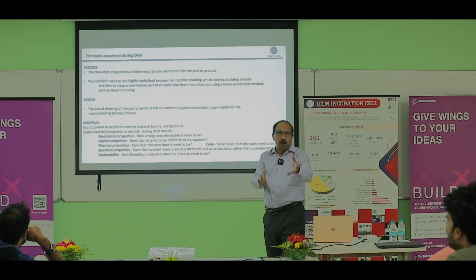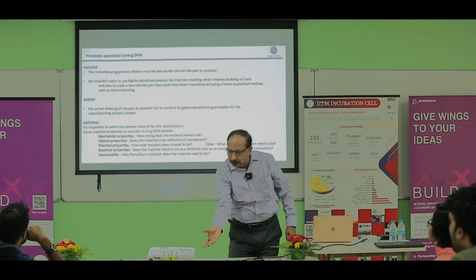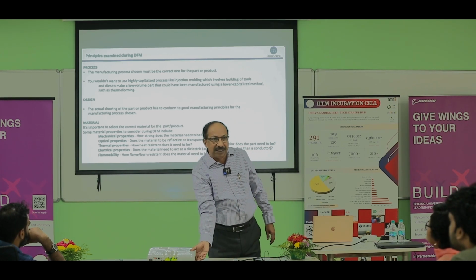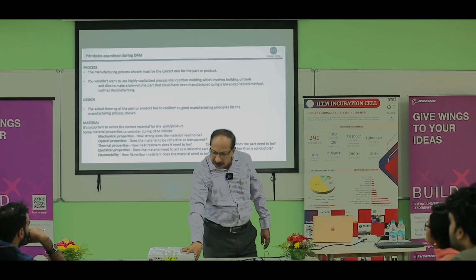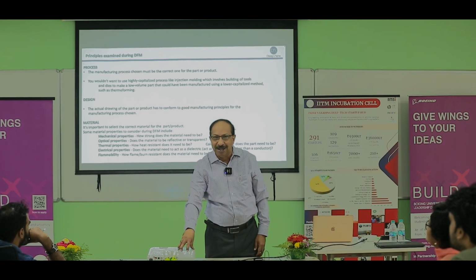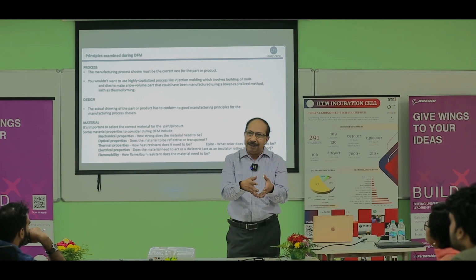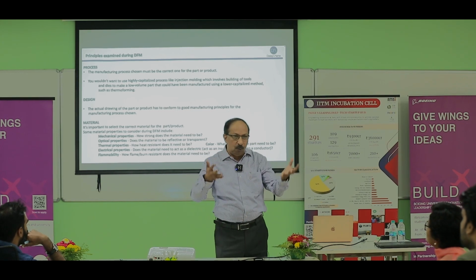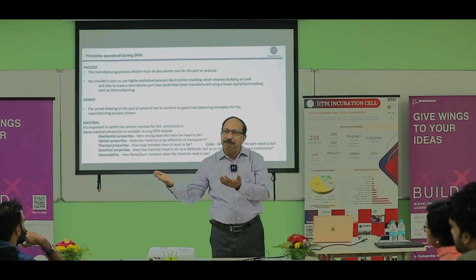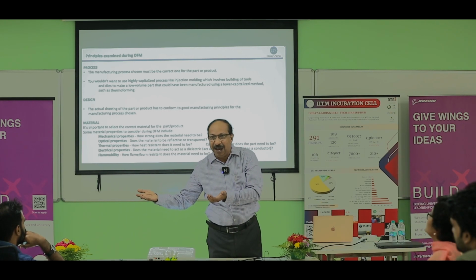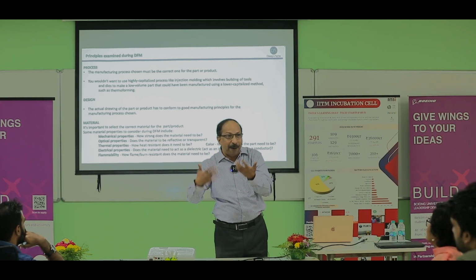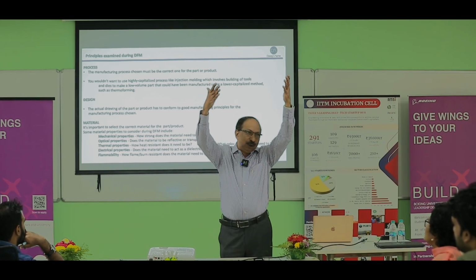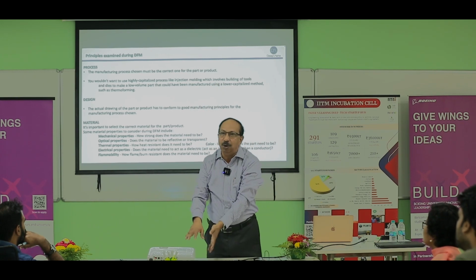One example is injection molding. If, for example, I am designing this one, this is injection molded plastic. The enclosure may cost 100 rupees. But if you want to make this by injection molding, you have to make a tool, a mold, that will cost maybe 50 lakhs. So that is how it comes. The part cost comes down, but the tool cost goes up. So unless you have volume, don't go for this.